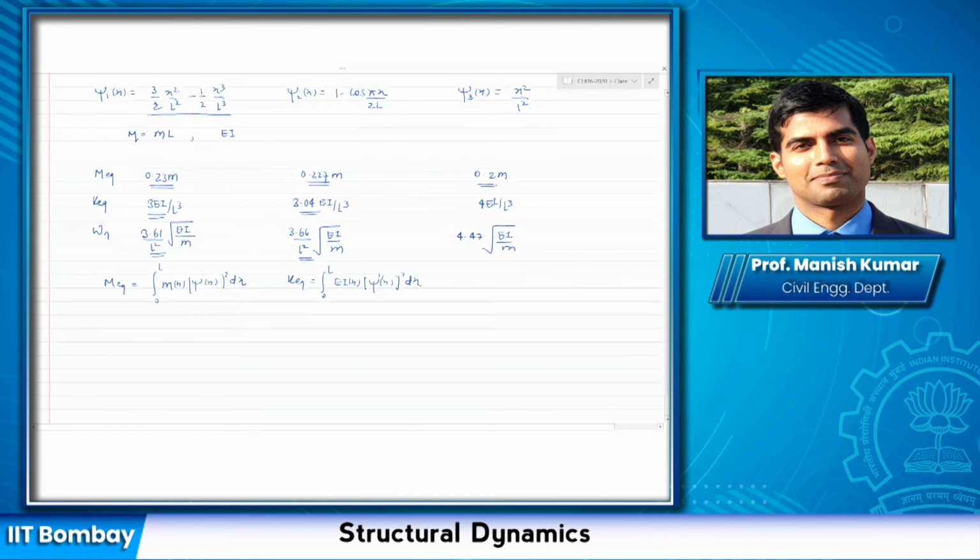Well, there is a beam theory, you can go and have a look at it, and there the expressions for the actual values have been derived, where the frequency has been found out as 3.516 square root of EI by M L square. Okay, and this was derived without having to assume a shape function or anything, just solving the overall equation. It is given in your textbook as well. If you go to chapter 17, if you are more interested, you can explore it. I'm just giving you this as the actual value without any approximation.